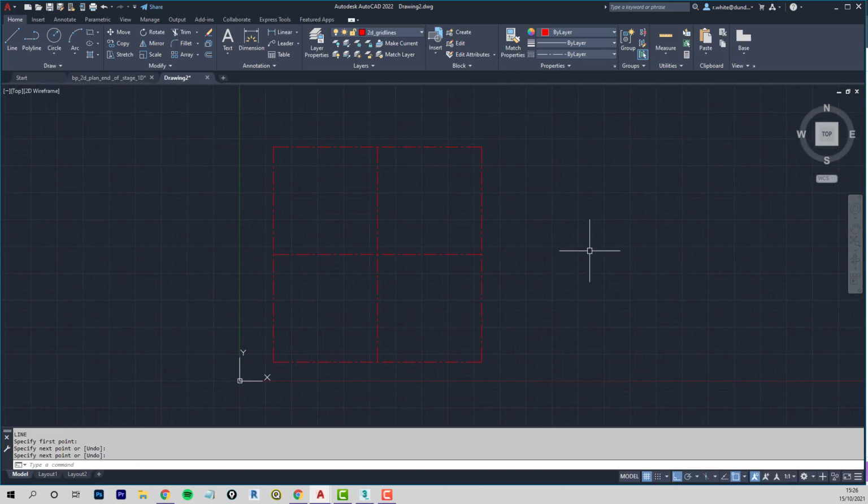Okay, now for my building, I'm needing another structural bay. So what do we do here? Do we draw a line out 5000, down 5000, back 5000? Not really, because we need the grid lines to be continuous. So I don't want to add fresh lines coming out this way. What I could do is offset and then create the corners. So I'll show you that way first.